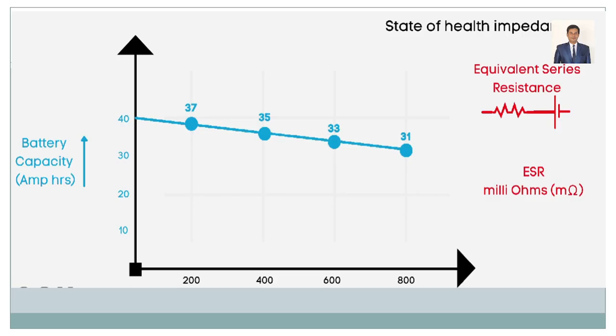Now let us consider internal resistance will also make a lot of impact, as already told, right? If the internal resistance increases, right? When you bought for the first time, the internal resistance was, I told, 50 milliohm. After 1 or 2 years or 3 years or 5 years, the internal resistance comes to around 90 milliohm. I mean there is a drastic change in the internal resistance. So how will it make an impact on the SOH also, right? And because of the rise in temperature, what will happen? Also, if the resistance increases, the current will drop. That is why the equation I is equal to V by R. If R increases, I will also decrease.